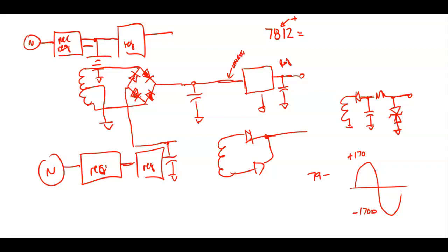First of all, we have an alternator out there. We have a rectifier. What are they using as a rectifier? It's diodes, right? Then we're filtering with the actual battery of the car itself. It makes an excellent filter. Then we run through a regulator, right? So this is really neat. You can look at the output of your car's alternator.